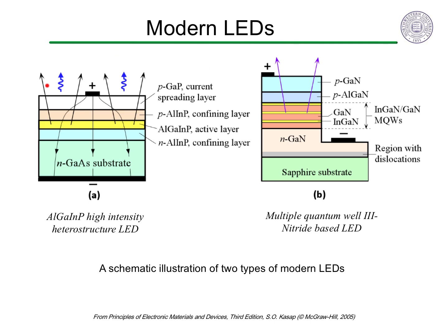The heterostructure LED has an active layer surrounded by layers with a higher band gap so the light can get out. The confining layers with higher band gap need to be doped sufficiently to inject the electrons and holes. The thicker substrate holds all the layers together. In this case, gallium arsenide substrate is used to make the aluminum gallium indium phosphide based layers.